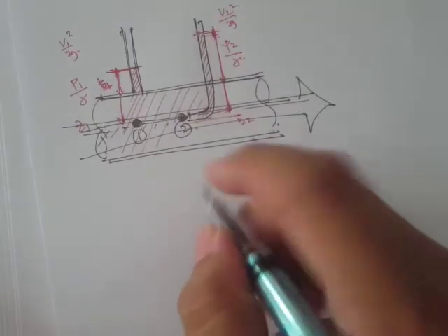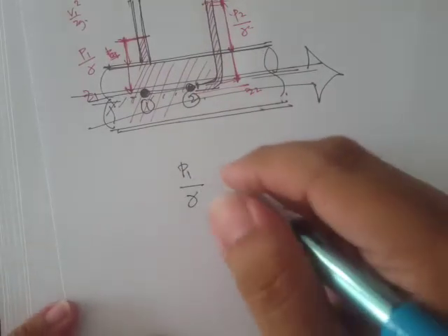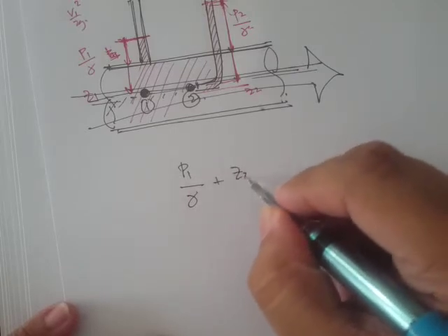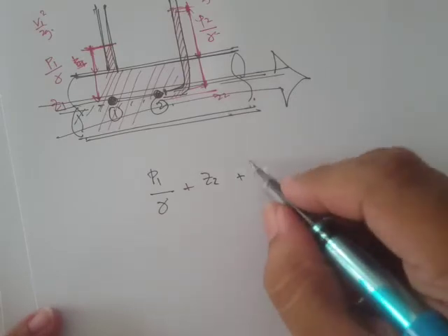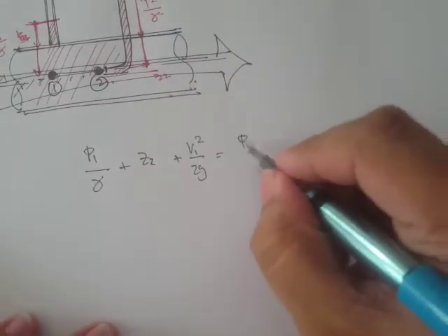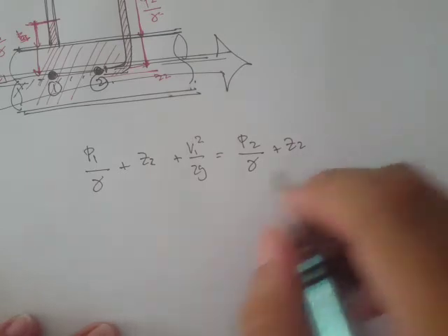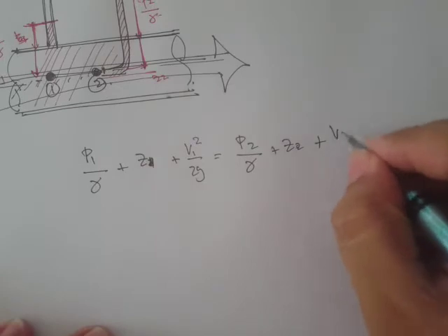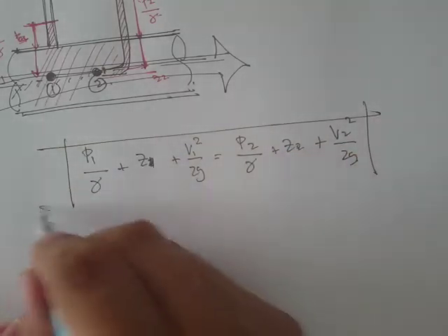Now, if we want to apply the Bernoulli's equation, then we have p1 by the unit weight plus the elevation head, plus the velocity head, v1 squared all over 2g, is equal to the pressure head at point 2 plus elevation head at 2, plus v sub 2 squared all over 2g. Okay, so just like what we did in the bank